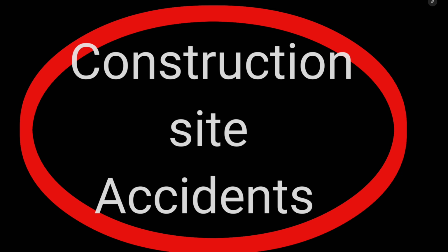Vehicle accident, especially in high traffic area like construction site, can be devastating. Establish vehicle routes, ensure proper training for drivers, and use high visibility vest and flags to alert others when vehicles are in motion. Prevention is key when it comes to construction site accident.